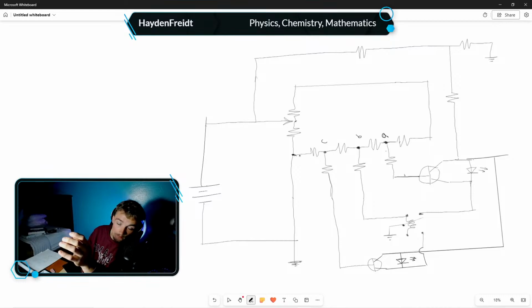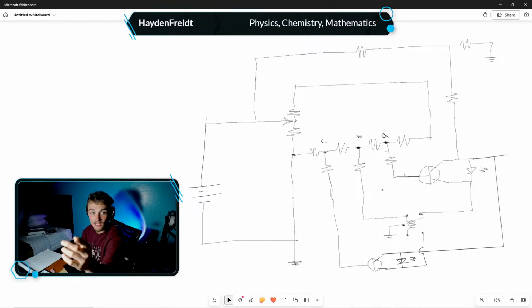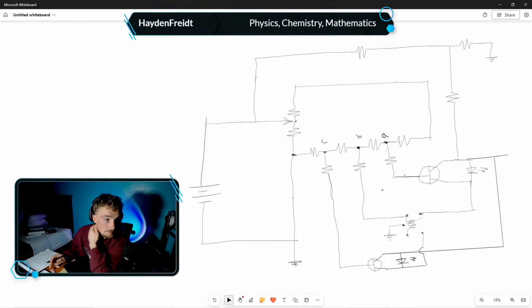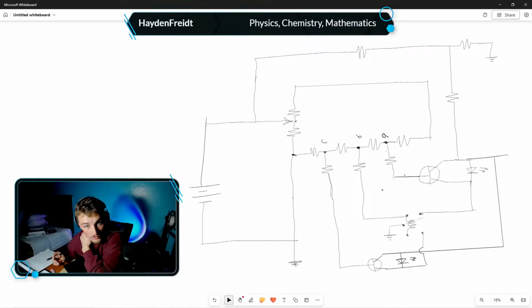And so now we're going to do an analysis of the voltage drops, and determine the amount of resistance we need to get a current which will activate the gate of our transistor, which the data sheet specifies as 10 milliamps. Maybe that's a maximum, I'm not sure. It says 10 milliamps, but I activated the transistor with as little as 3 milliamps. So we're going to stick with that. We're going to use 3 milliamps as a guide. That's what I'm going to say activates the transistor. So that's what we use.